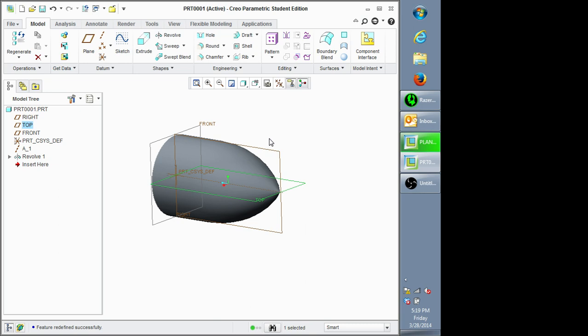There's other tools that will actually expand your thing, but at work, I actually use the extrude tool more than the revolve tool most often. You can also use the revolve tool to create holes sometimes. That's another method. Say you have a surface that's kind of hard to get to, or you have to create a customized counterbore or countersink for a part, you can use the revolve tool to do that. I'll show you how you can do an extrude cut using a revolve cut.